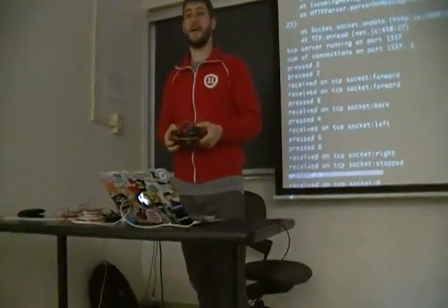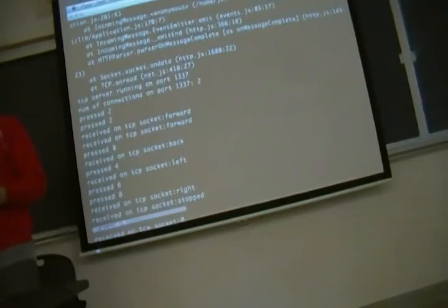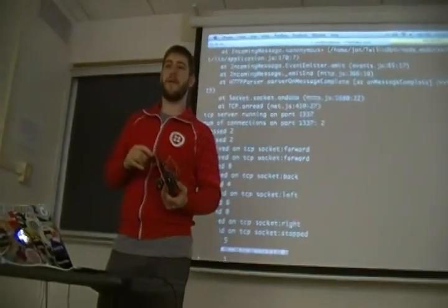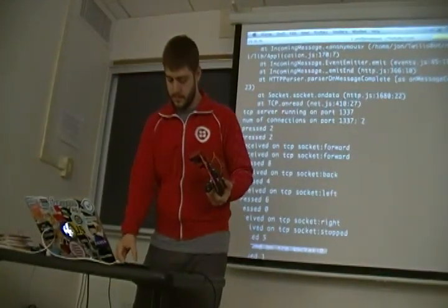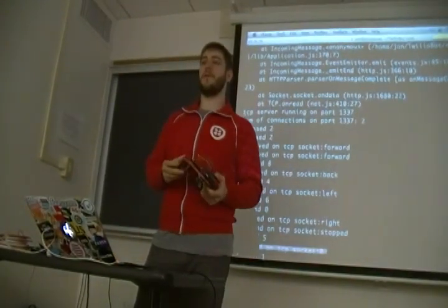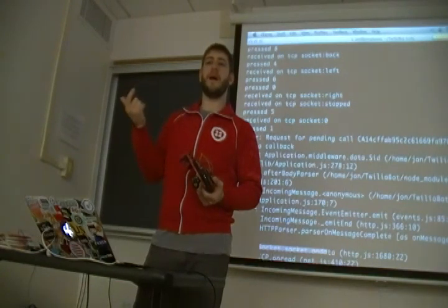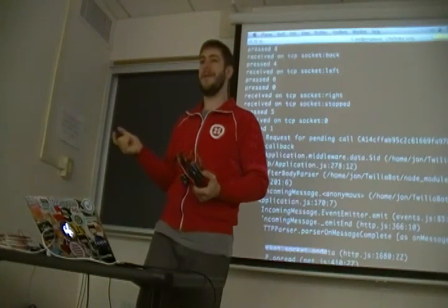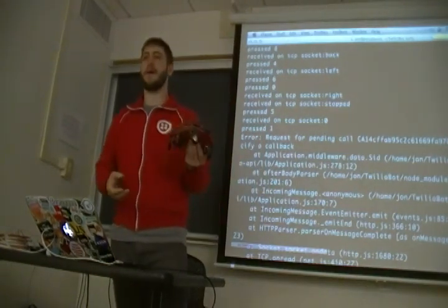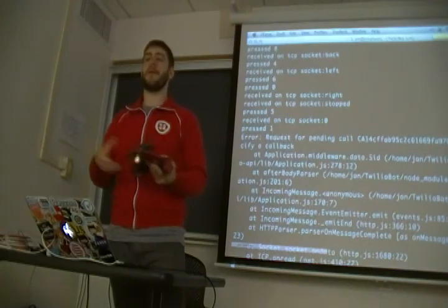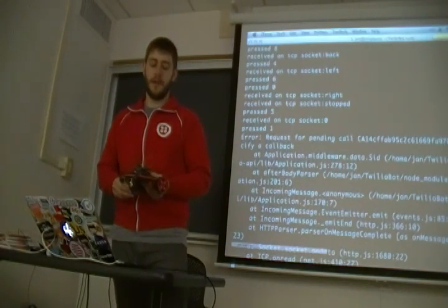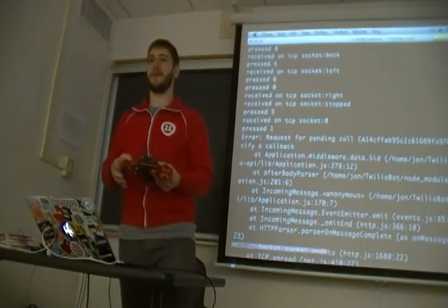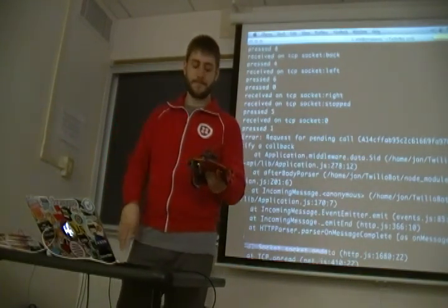Yeah, that's basically it. What values are you testing on the servos to get this done? Every continuous modified servo has a mid value. Do you have to guess and check? Yeah, you basically have to guess and check. It's usually around 90, but not usually exactly 90. I think for these it's 91, and you just play around with it until you find the stopping point. If you use a normal DC motor though, you just stop the voltage to it, and it just doesn't move anymore.